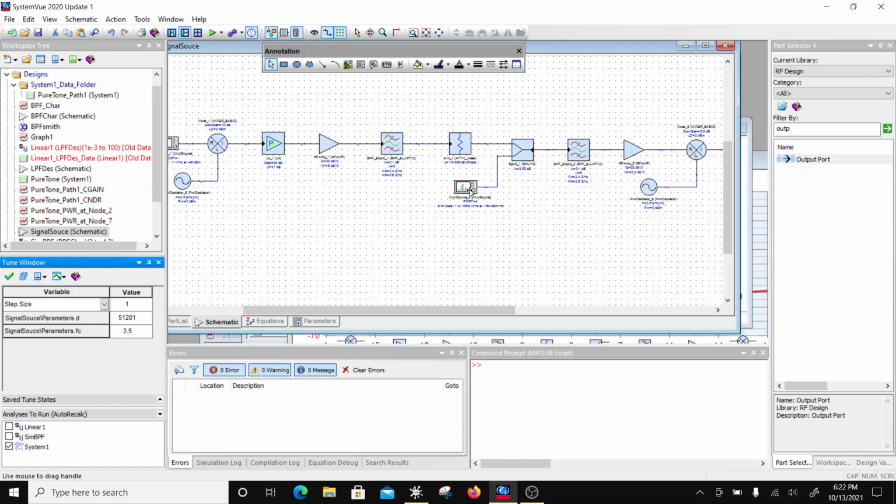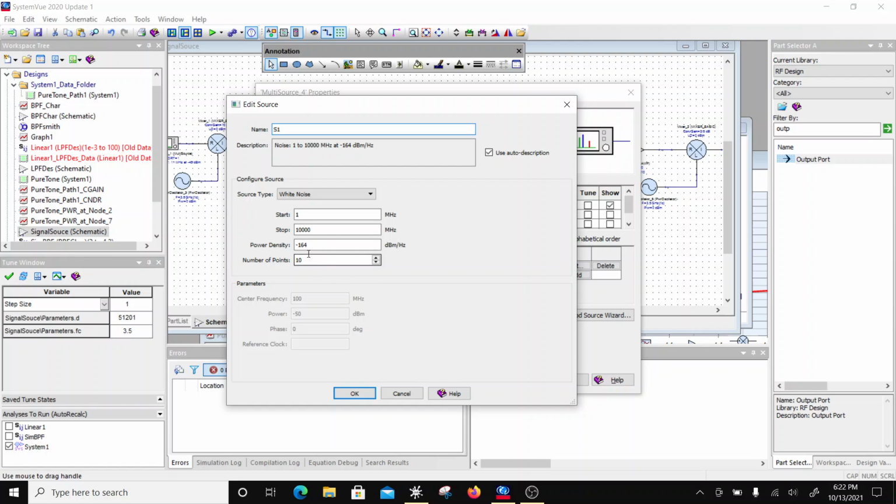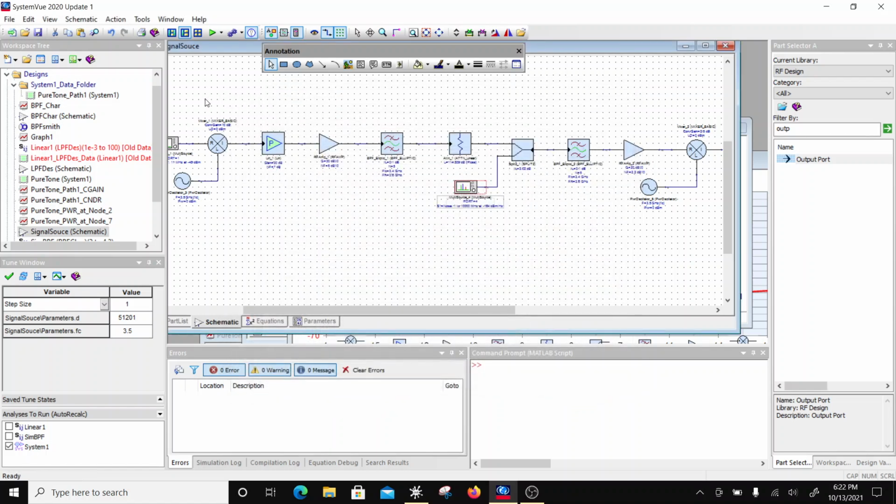For example, you can bring down the noise. Well, you are looking at the worst case scenario. For example, I'm adding 10 dB noise above the thermal floor. Had I brought this down, for example, I can put another tuner and bring this down to the thermal noise case, minus 174.